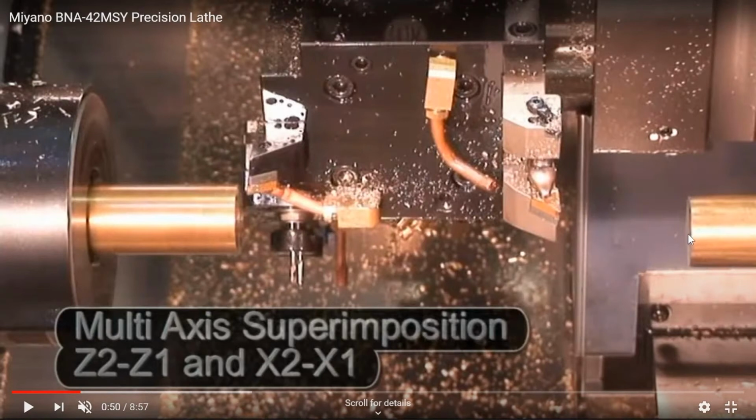Basically, the offset on the part over here, changing the X and Z, usually on the machine doesn't change the work offset. So if you change the part position from this position to this position over here, on the machine the G55, let's say, will still be over here. It will not dynamically update. So the superimposition, as I also mentioned earlier, is like a dynamic work offset. Let me just run the video.